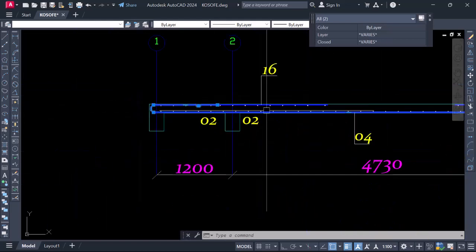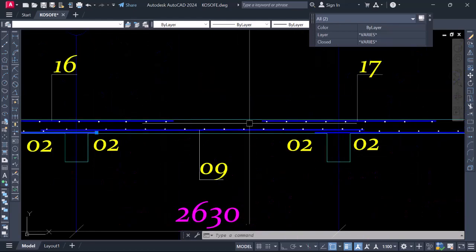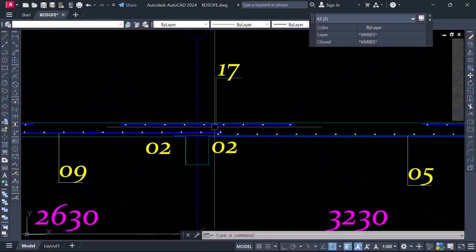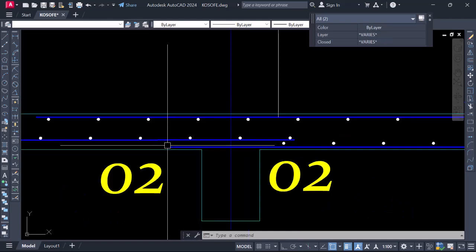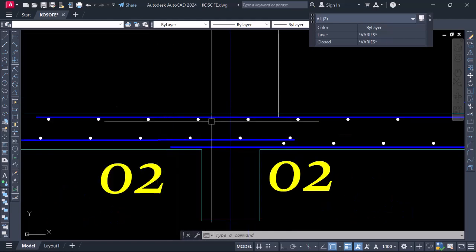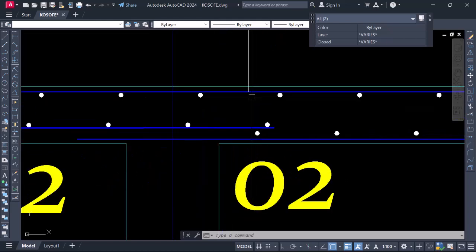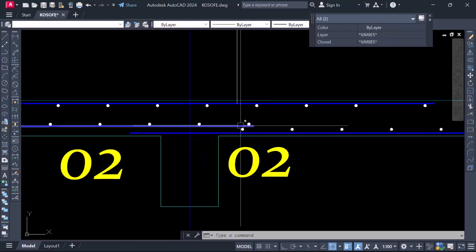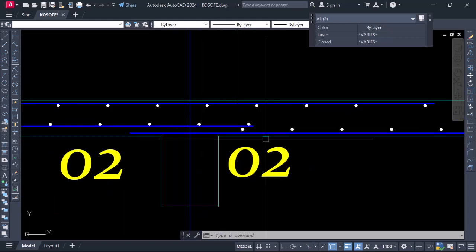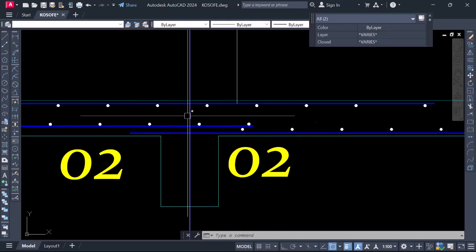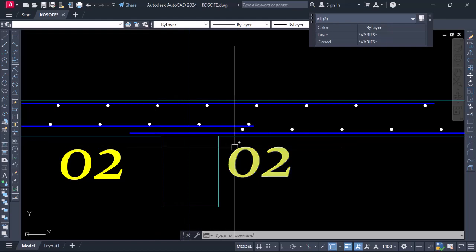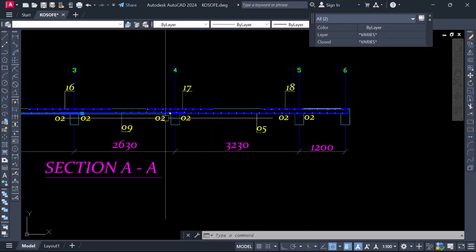So this is going to guide you on site while you're doing your sectioning, alright? This is termination, and you consider extension, alright? Extension of 30 exceeding the beam line, right? And on this other side, you can see that there is an extension. So by the time you have your 30 over here and 30 over here, including the beam depth, the beam width, okay? So you don't have to worry about your lap length when you have a beam section.